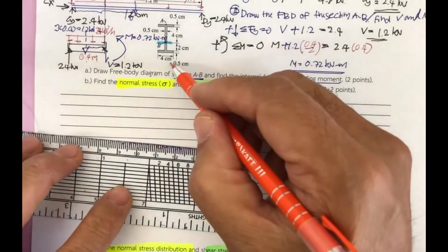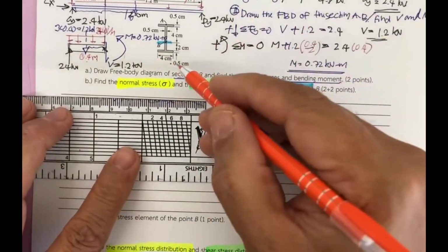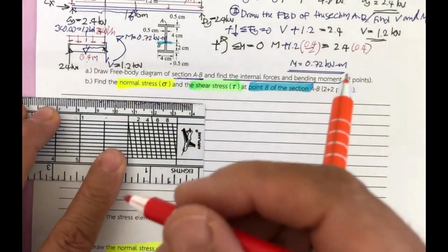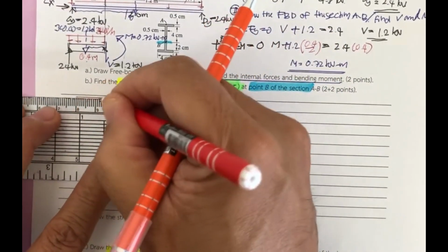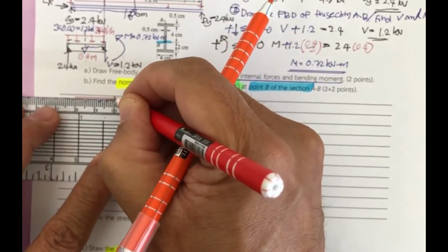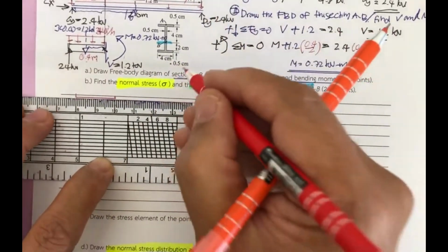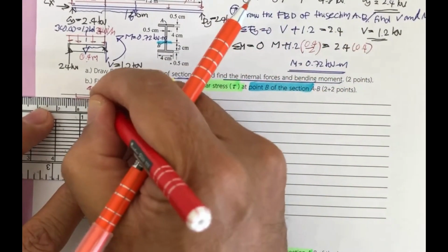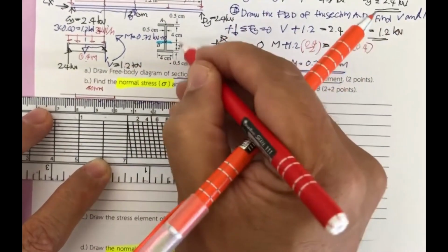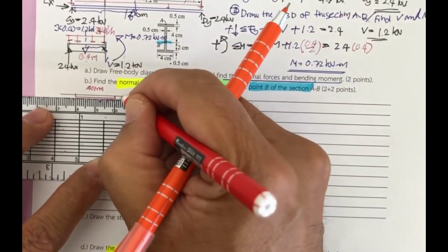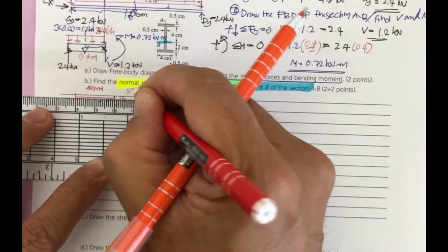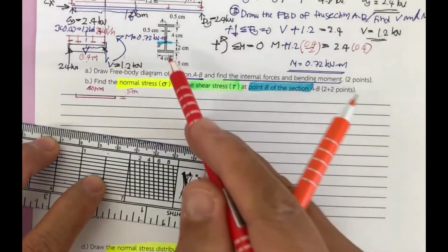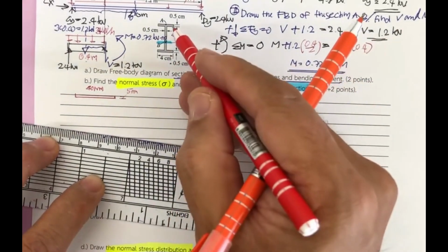Okay, this is 4 centimeter or 40 millimeter. Let me put this one in scale. Let's put this one for 2 centimeter. That is going to be a scale of half of this. This is 4, this is 2. This is going to be 40 millimeter. And the thickness of this is 5 millimeter. That is going to be the top portion of this section, or this is the top flange.